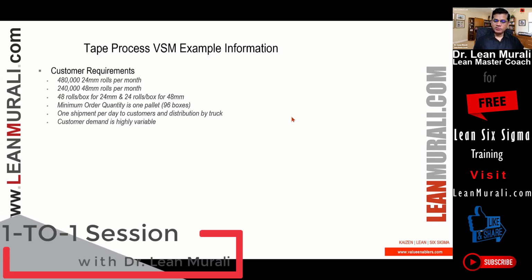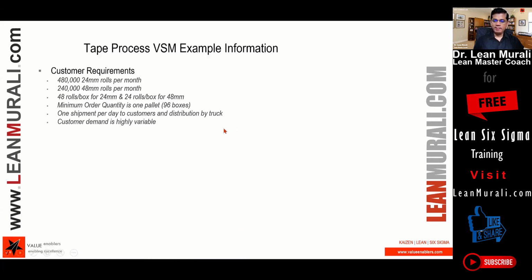And I've added some extra information: the demand is highly variable. The reason I've added this information is that when the demand is highly variable, you should always consider, during the takt time calculation, when you take the average customer demand, will you take it on a seasonal basis, a monthly basis, or a weekly basis?